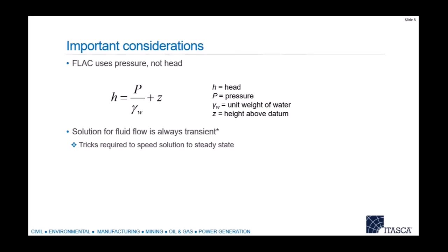For those of you who've done some theory, a lot of time people work in terms of head, which is kind of like the height of the water table. FLAC2D does not work in head. FLAC2D works in pressure. So you can move from one to the other, and thanks to Joe, you can now plot head in addition to plotting pore pressures. But know that fundamentally, FLAC2D works in terms of pore pressures at the nodes, not the head. Okay.